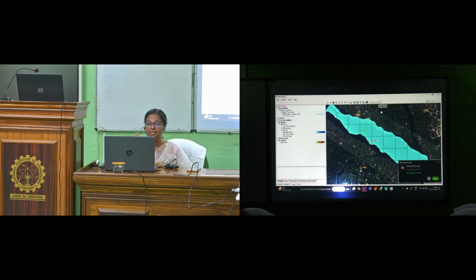The elevation data is taken from the DEM we provided. So DEM data is very important, but actually you have to pre-process it in QGIS or ArcGIS and do all the filling. You have to do it in the GIS software and import it here. I have not done all those things, that you have to do. Because the DEM image is very important, and you can even give the actual field data for cross sections and all. That also you can put here.